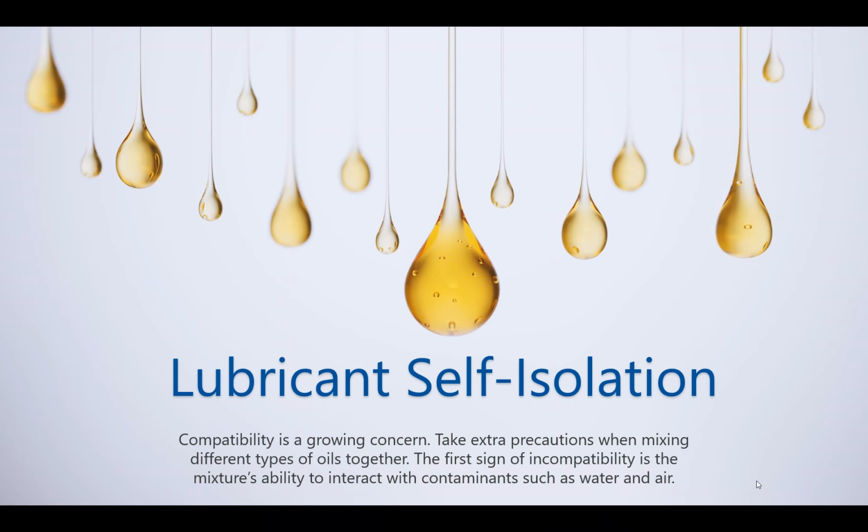It's clear that compatibility is a growing concern, and not only between new oil types. New oil is new oil, and therefore there exists an ASTM standard, D7155, as a practice on compatibility testing. But it's also a compatibility issue between new oil and used oil. Think about remaining oxidation and degradation products which are then coming in contact with the new oil, where you can see first signs of incompatibility in the mixtures, such as air release or water separation characteristics, which can certainly have their impact.